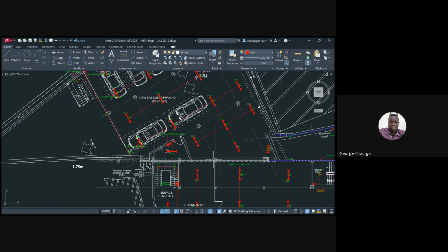You can go online and search, but let me design based on an LED bulb. For an LED bulb of such a linear lumen, 1.2 meters, the least would be about 10 watts, and the maximum we wouldn't exceed about 15. You can go on Google and really search.